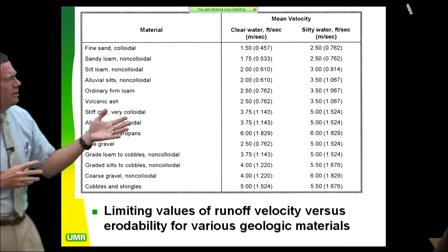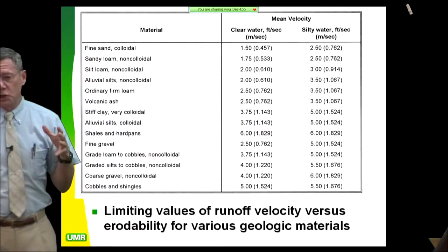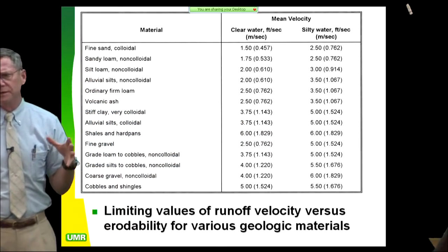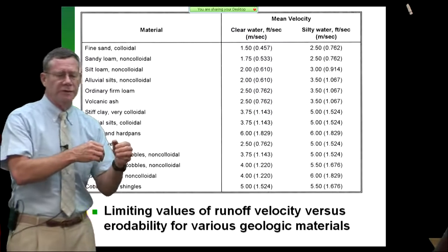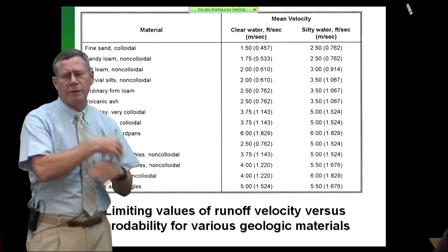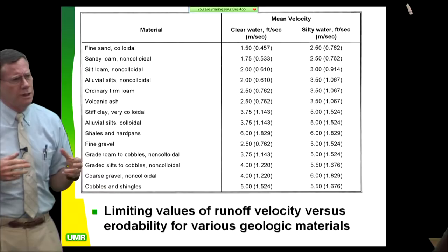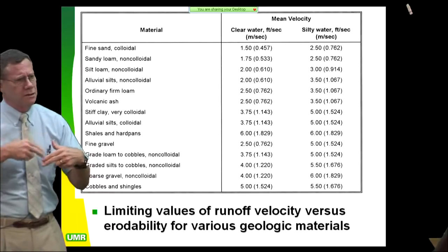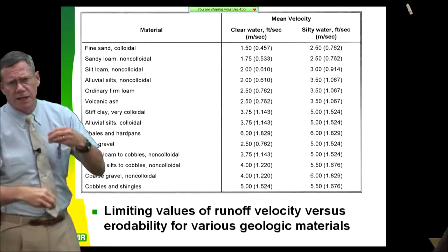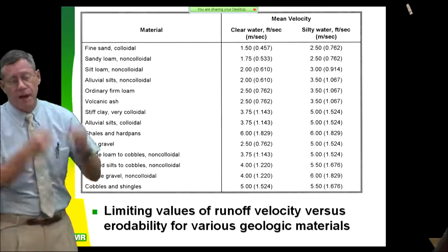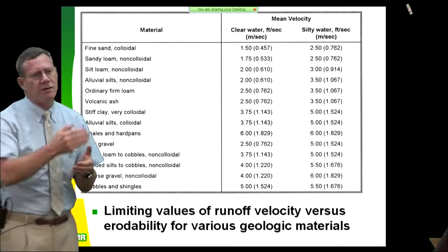And what this doesn't show is stream power. Stream power is the Q you're looking at, the quantity of flow and the duration. So the longer you have it moving there, the more things are going to start to move, transmit kinetic energy from one particle to another, and things are going to start coming unglued. Now when they start coming unglued, then you get roughness. You have places where it gets very, very rough, and you're going to get negative pore pressures and stuff pocking out, and the erosion, once you get to that point, goes very, very rapidly.